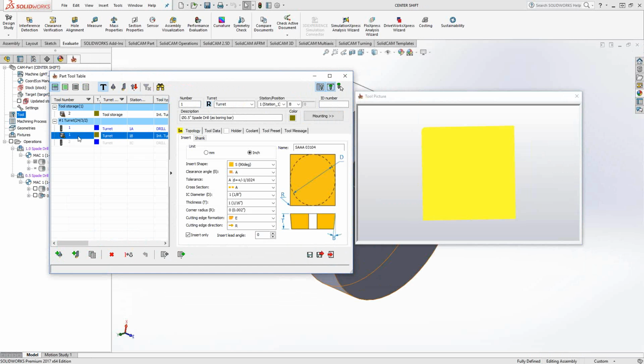For the second tool 1, the one that I'm using as a boring bar, I've actually just defined it as the insert only, because in this case, I'm just doing turning. I know the size of my insert drill. I'm not really worried about collisions or anything like that. I'm just finding something that approximates the tool. In this case, it is just an S-type insert. The 90 degrees, I've set the insert angle to 0, so you can see here it's essentially just the insert itself, just floating in space, because I set it as insert only.